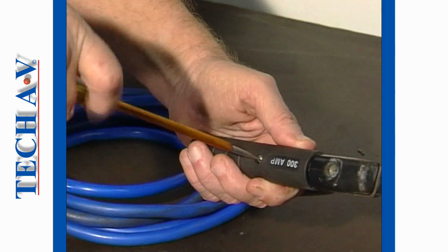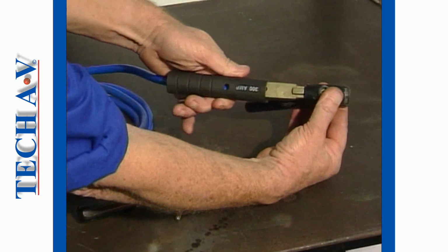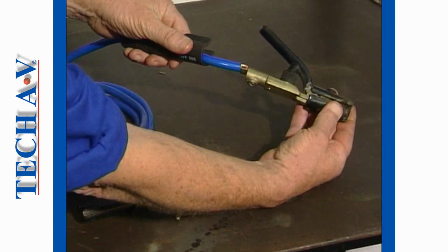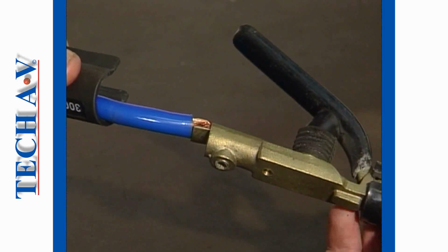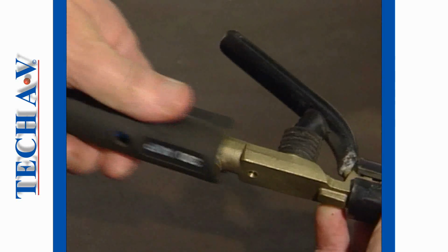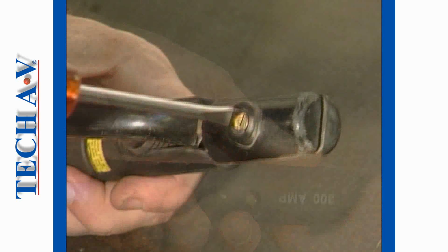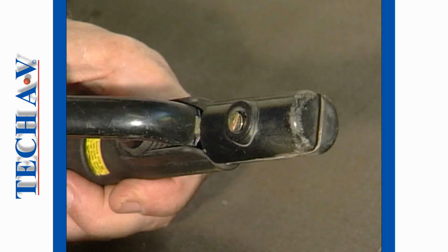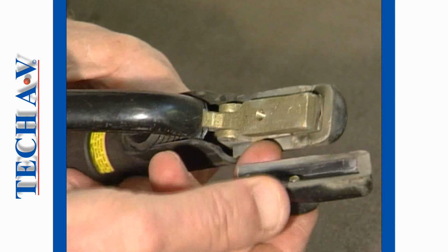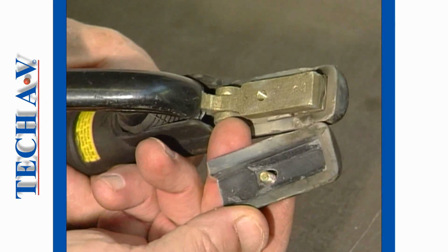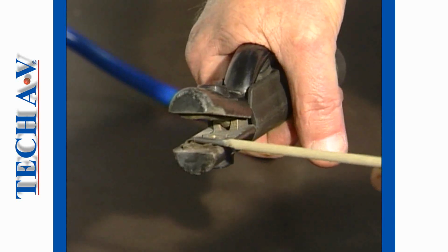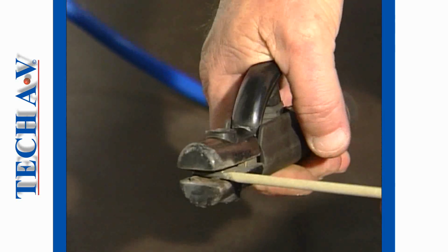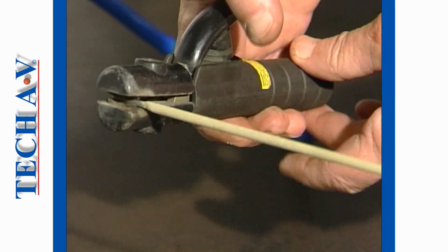The electrode lead terminates inside the electrode holder. The conductor core is secured into the metal head section. Insulation is provided by the handle which slips over the lead connection. Further insulation is provided at the electrode end with replaceable nose insulation. Spring-loaded contact jaws create the electrical connection to the bare wire end of the electrode.